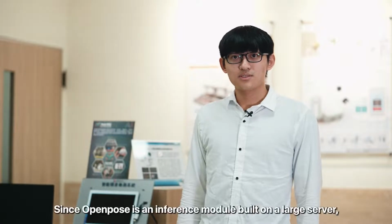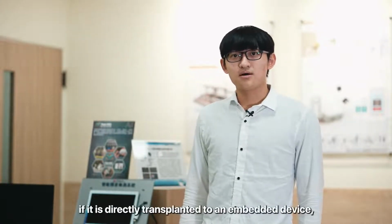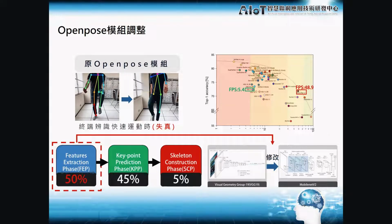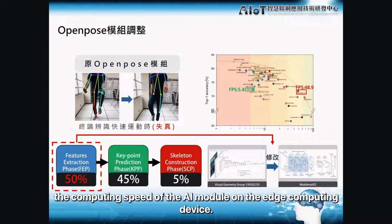Since OpenPose is an inference module built on a large server, if it is directly transplanted to an embedded device, there will be a problem of insufficient computing power, which will result in blurred images during fast motion, making some joints unrecognizable. Therefore, we have modified part of the neural network and replaced the original heavy VGG19 with the relatively lightweight MobileNet V2 to reduce the overall calculation amount and speed up the computing speed of the AI module on the edge computing device.